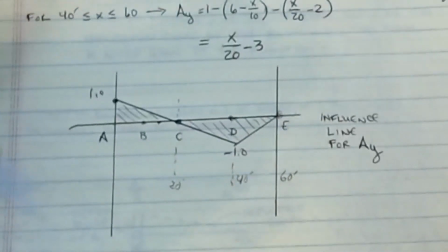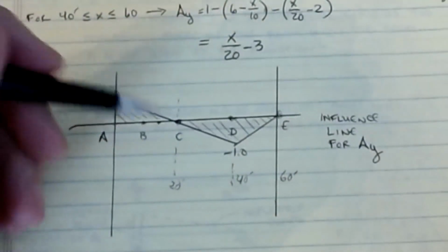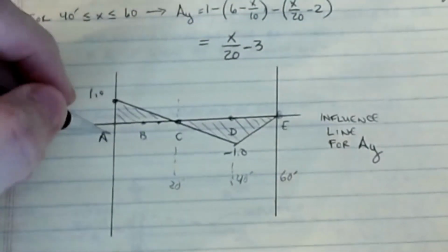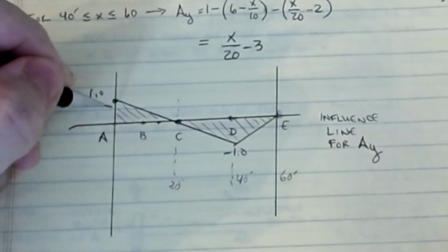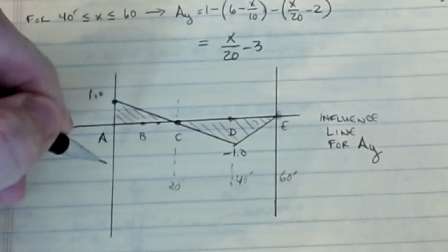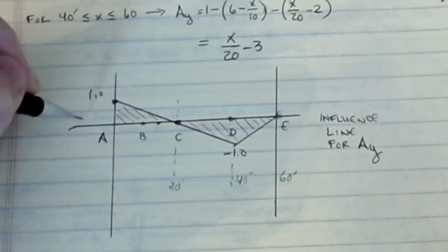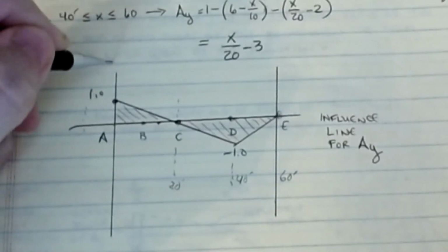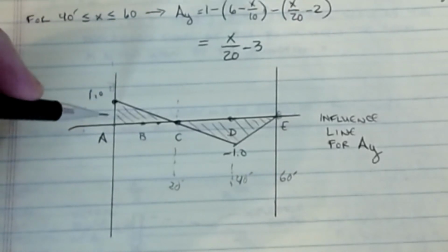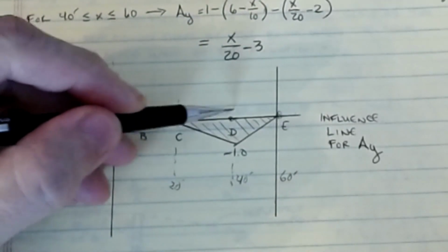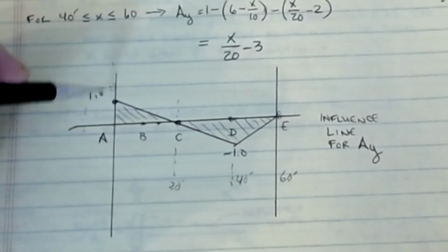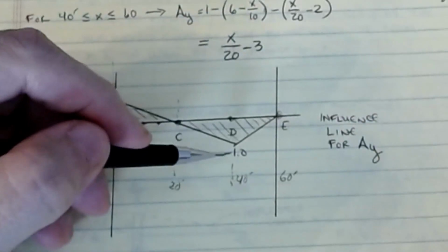But these pictures can get very complex, and they can start to ramp up and become increasingly more complex. But now you have the ability to figure out, on my structure, maybe I'm looking for the case where the maximum positive load in this footing, or maybe this is a column in a building, that the worst loading for the compressive side of this column is when the point load is sitting right here. Whereas if I put the point load out here, I could actually get a negative effect, which could be a tension or an uplift on that support because of the negative one.